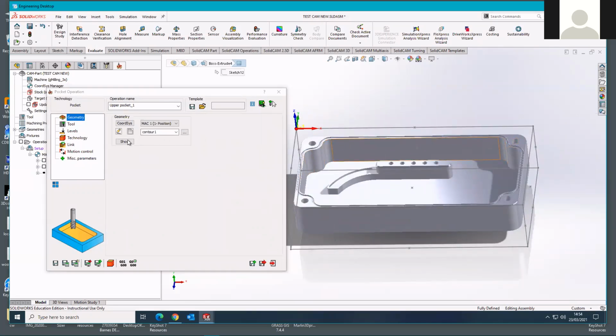I'm going to have to create a new set that contains both that first chain, which I'm going to have to replicate, but then also contains an island in the center that I do not want machining. So I'm going to have to create new. So I click on the new icon again.